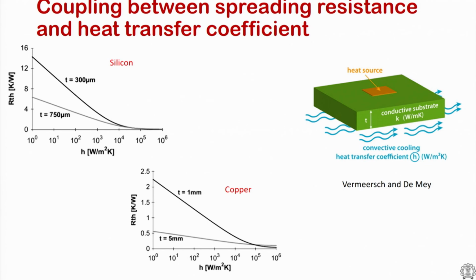For example, for a thickness of 750 micron, even though your cost has gone up so incredibly, the change in thermal resistance is only half. Because you are putting in fans, you have a fan that is a cost adder, and you have to put in a larger heat sink and so on. Even though your heat sink size and fan size have increased, the improvement in thermal resistance, having moved from natural convection to forced convection air, is only half.